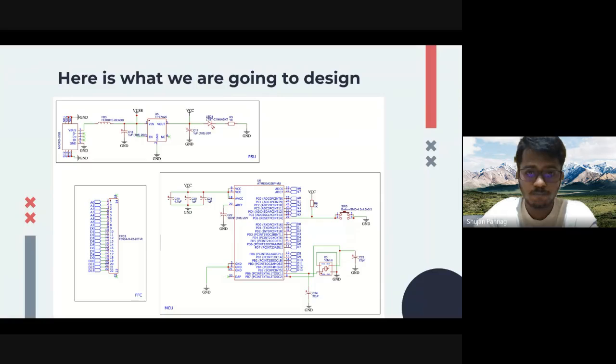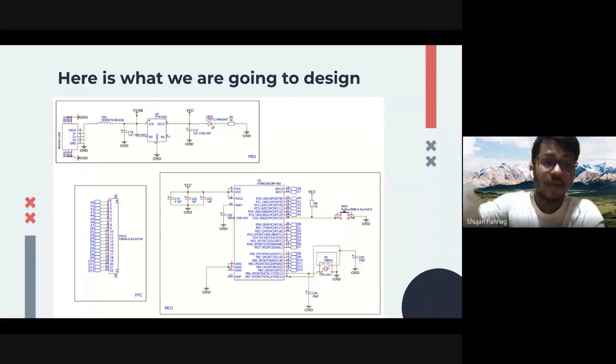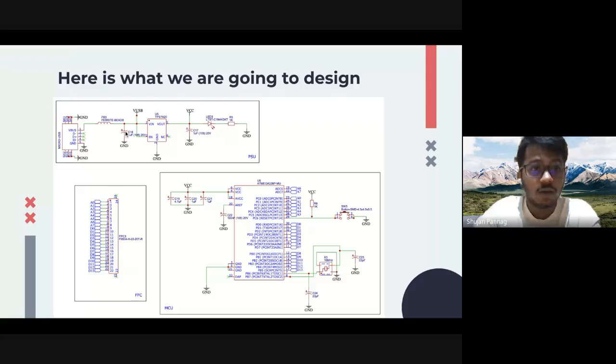Since these are very low power devices, you need a power regulator with low inrush current. Inrush current is the current sunk by the regulator when you power it on. It should be really low, or else there'll be a spike in the output, or there can be heating issues in the starting phase of powering on.